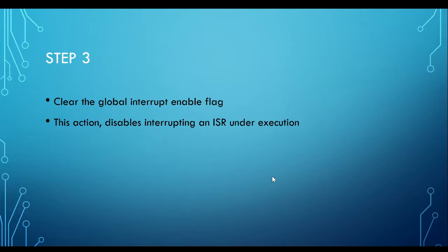Okay, you clear this action disables. Now, your interrupt can only happen one interrupt request at a time. So when you are servicing one interrupt, the other one will have to be queued or will have to be waiting. So in this short period where the interrupt service routine (ISR) is being executed, in this very short time, probably point something microseconds, the GIE is temporarily disabled.